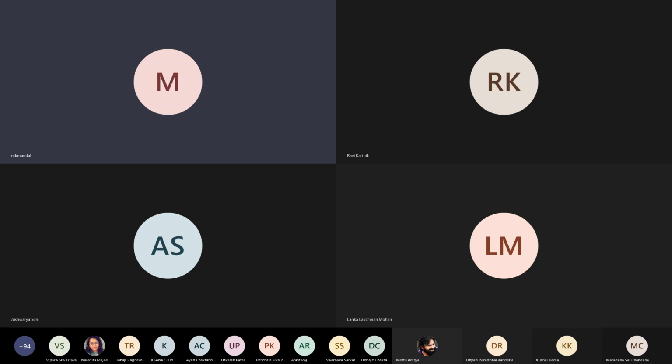We can also have TE01 mode. But if you look at the electric field components, they are orthogonal to each other. The corresponding magnetic fields create loops encircling the electric field component, and those lie in planes which are again perpendicular for these two modes.